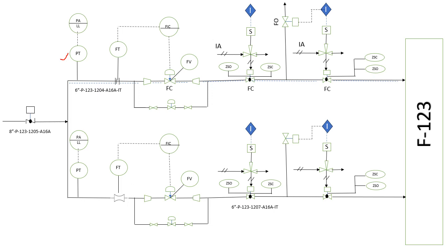Similarly, this FT is going to a closed loop controller and controlling the flow through a valve. Also, the valve here is a reducer. You can see the size of the line is mentioned by this nomenclature, like 6-inch, and the valve size is reduced. It also mentions the type of valve through the symbol FC.